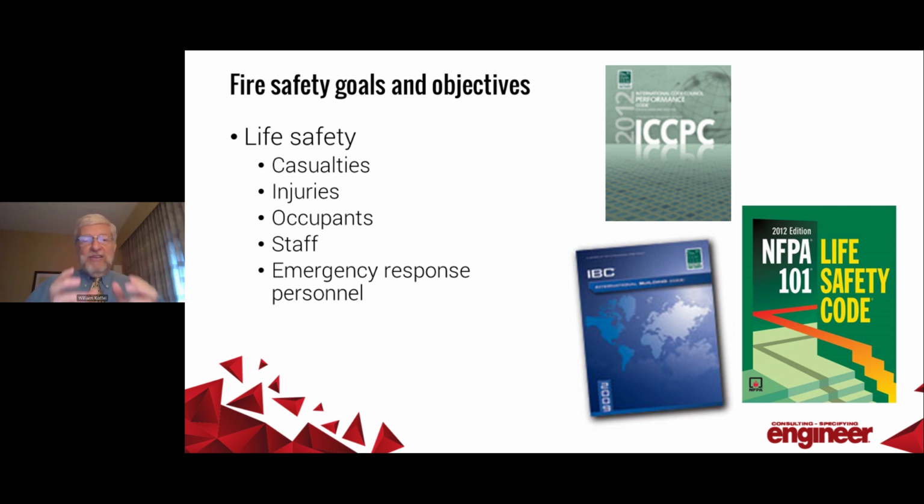And the life safety goal for most people would say the various codes, and I know I use some older editions there, and I do that for a point. First off, make sure you have the correct, appropriate edition of the code for that jurisdiction. And then as a design professional, because remember, our standard of care goes beyond just minimum code compliance, it might be appropriate to look at some newer editions of the code.